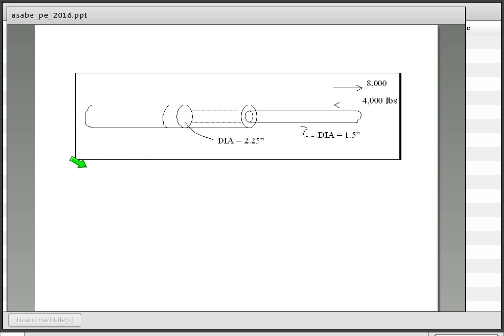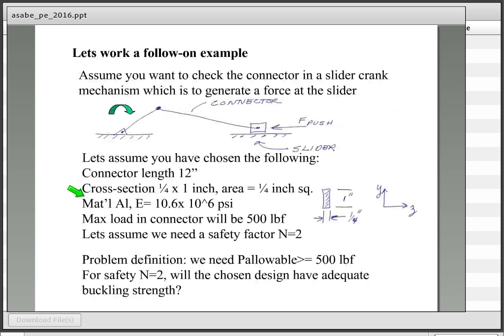If you're asked to calculate push or retraction force capability, you just want to have an understanding of what you're looking at with a cylinder like this. You can have double-ended cylinders where the rod goes out both ends, and then of course you'd have the same area on both sides of the piston, and that would not be an issue as far as the differential.